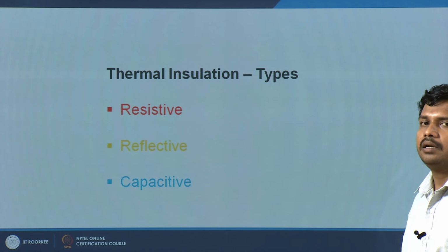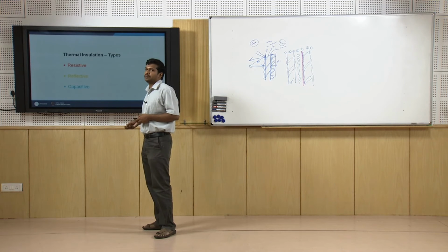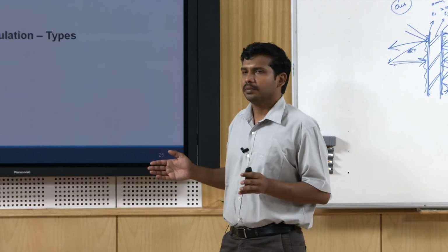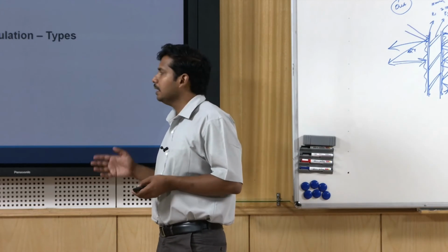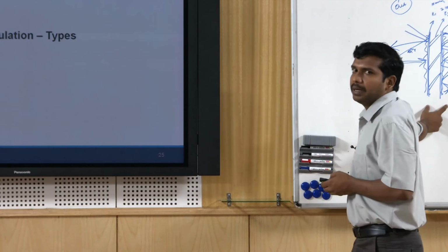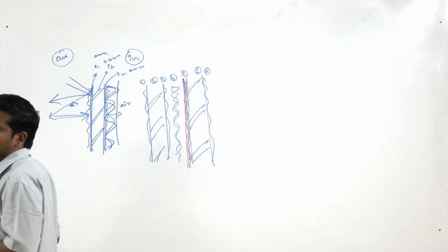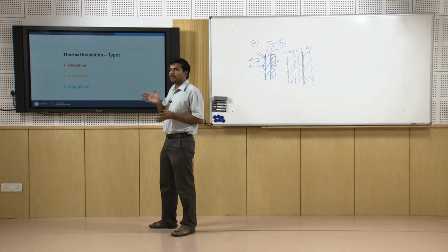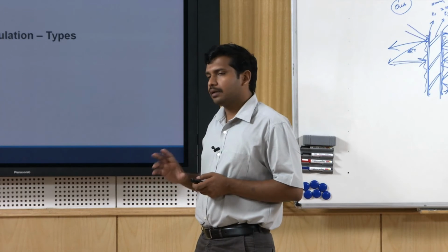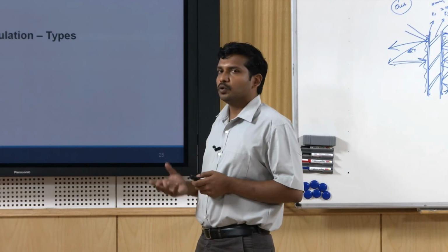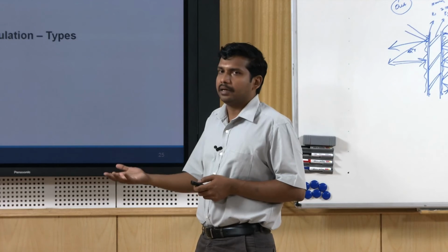The third or most rarely used insulation type is capacitive insulation. Traditional architecture, India especially, has been relying on capacitive insulation. You see materials like granite, thick walls, massive earthen walls being used in buildings. They were a kind of capacitive insulation. They were taking advantage of the material's thermal capacity and its density in storing heat. The wall gets heated up and stores a lot of heat inside before transmitting it indoors, and in the evenings, when the diurnal temperature range is much larger, the night time temperatures are pretty low. So before it gets transferred inside, it is re-radiated outside.